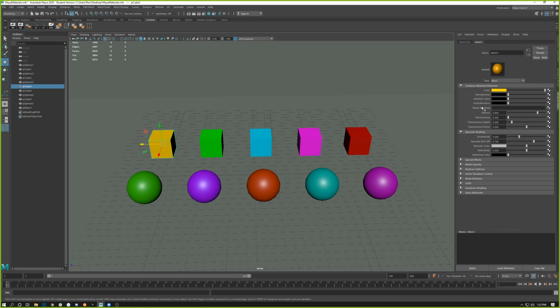Bump mapping is amazing, but that's going to get its own section lecture. But what it is, in the broad sense, is it uses some sort of texture and a light to mimic geometry that's not actually there. So you can actually fake geometry by using some sort of input, like a texture node, and light to kind of fake things. It's really good for surface detail if you want to add cracks on something or little grooves or anything like that. That's a great way to fake those things without actually having to model them out. So I'll show you how to do that.